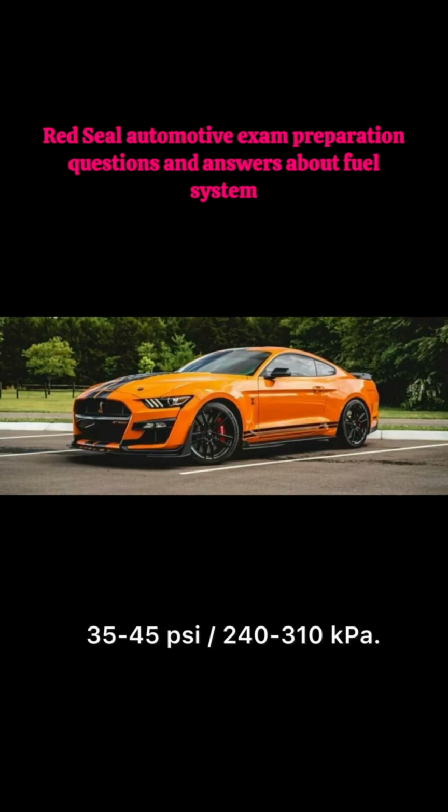5. P0171 lean. Fuel system cause. Weak pump, clogged filter, low pressure. 6. Tool to check fuel pump volume. Graduated container and timer. 7. What is deadhead pressure? Max pressure pump makes with return blocked. 8. P0442 code means. EVAP small leak detected.